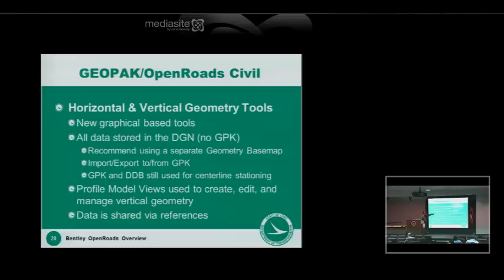So because of this, and I mentioned earlier in the CAD manual, it only specifies 3 base maps are required: one for existing, one for proposed, one for right-of-way. All the other base maps that are listed in there, like for drainage items, for traffic signals, for whatever, maintenance of traffic, you probably want to do separate, but those base maps are optional. So we're going to recommend that the geometry itself is stored in its own file. So there will be a base map added for purpose of geometry.